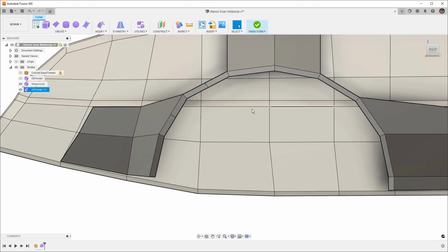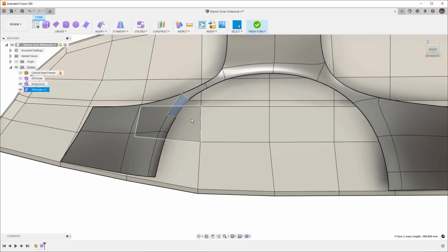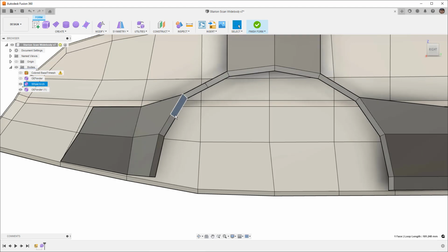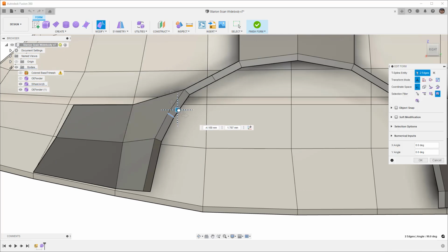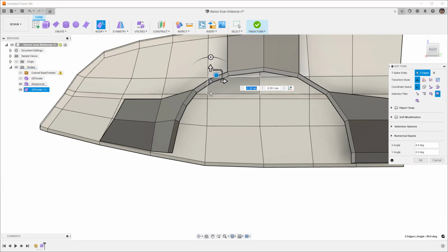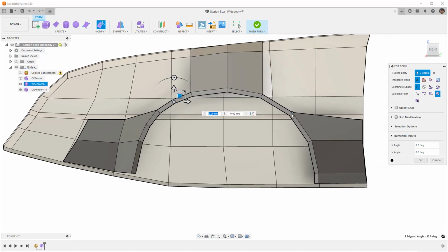Remember, when we use the simple insertion mode, it's going to do those completely flat. It's not going to change anything here, which means when we go to a smooth display, we're going to be messing up the curvature in that area. So what you want to look for when you do this, if you're happy with the position of that edge, you're going to be moving these so that you have a gradual change in curvature between all the edges. And what you're probably going to find is that you need to do this on both sides or all sides, and then just double check your smooth display.